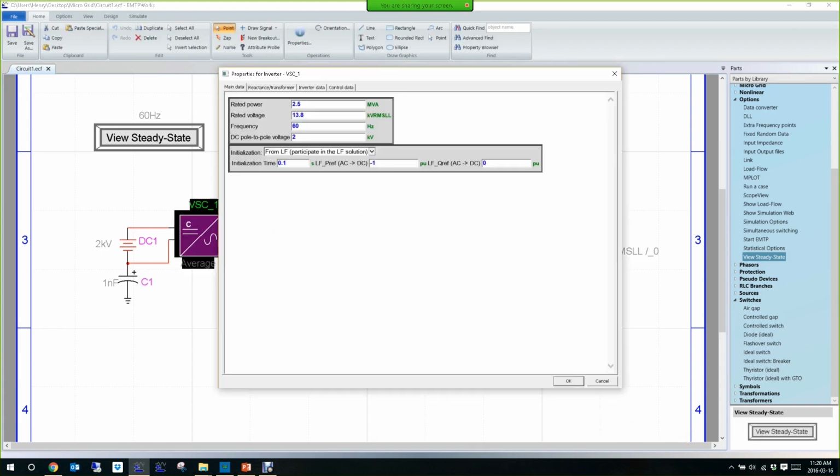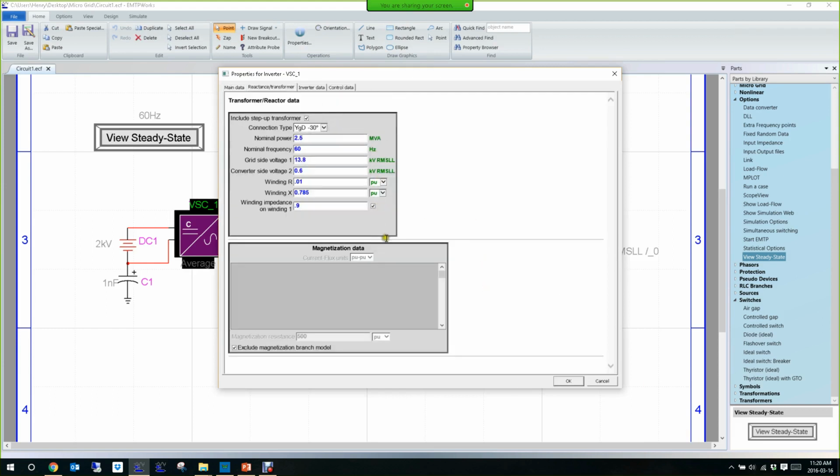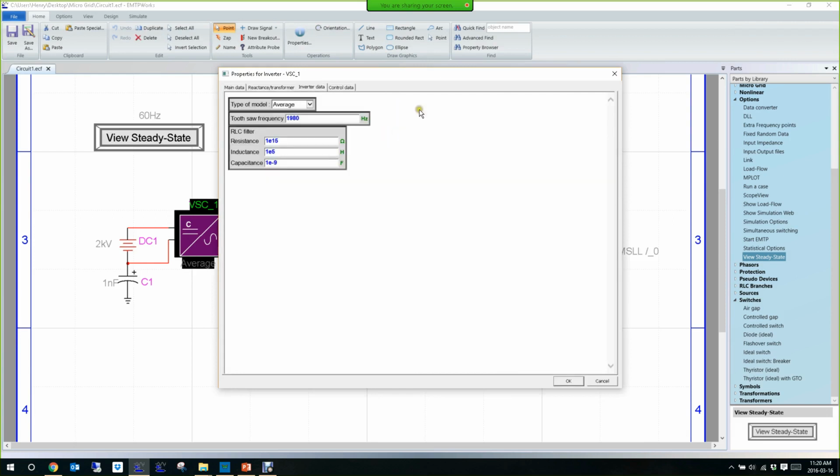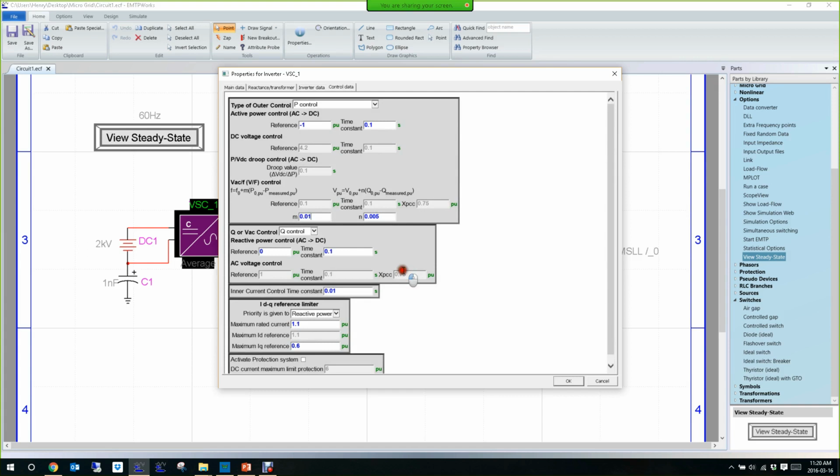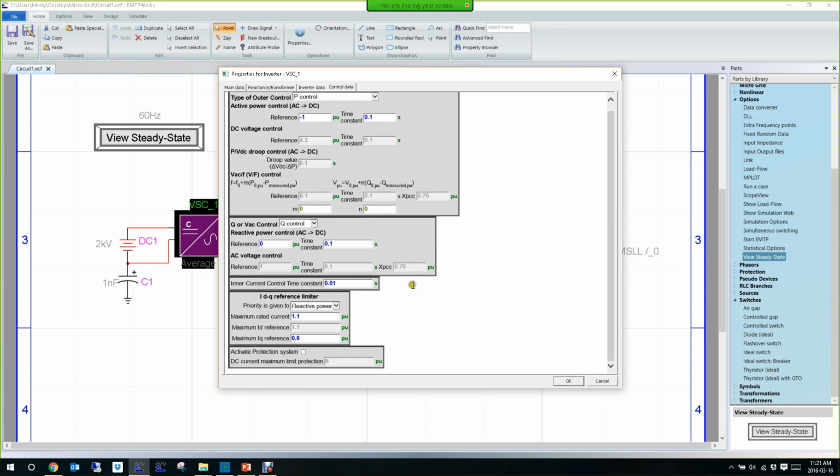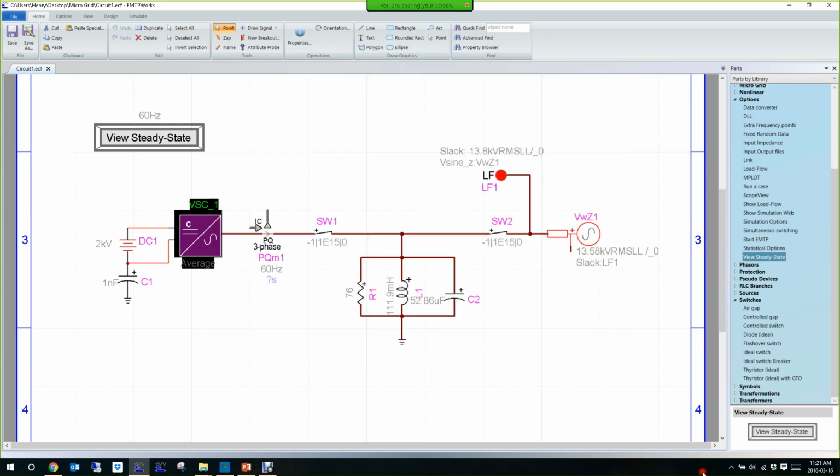Okay, so I'm good to go. Let me double check quickly all the parameters entered in here to make sure I haven't made big mistakes. We'll see it very fast if I did, but if we can avoid that. Oh, here's one. I have to put 0 here. What is that? It's two parameters to do the droop control in the VF mode, in islanding mode, when you have several DGs on the same microgrid. We'll see that later, but for now I put them at 0, so I control directly the voltage and the frequency. I think all the rest is fine.